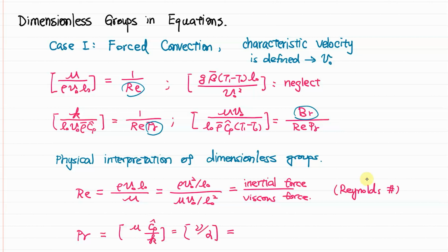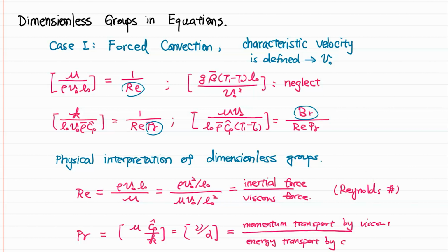So it's a measure of the momentum transport by viscous mechanism over the energy transport by conduction. So the Prandtl number is solely dealing with the molecular mechanism.